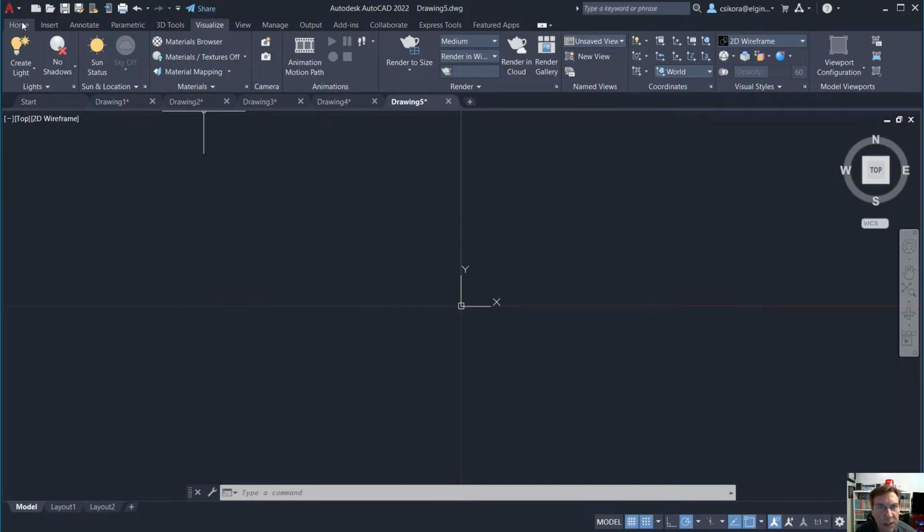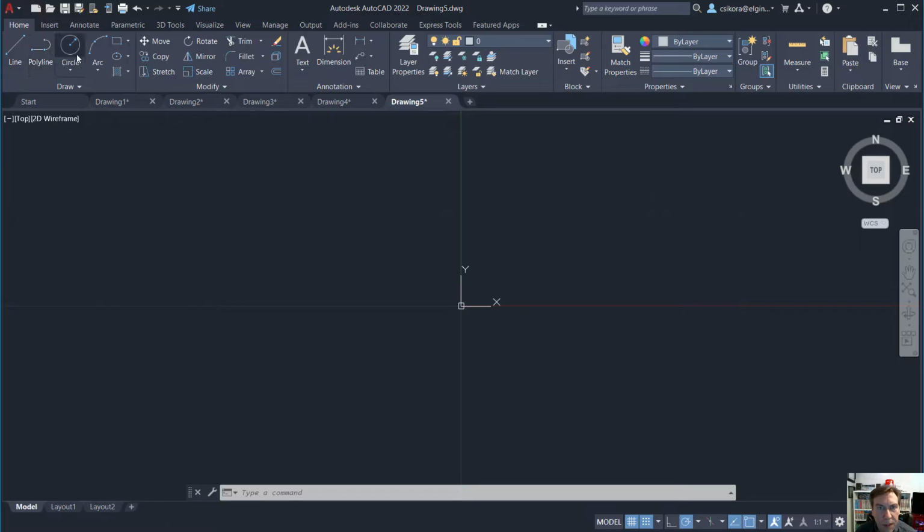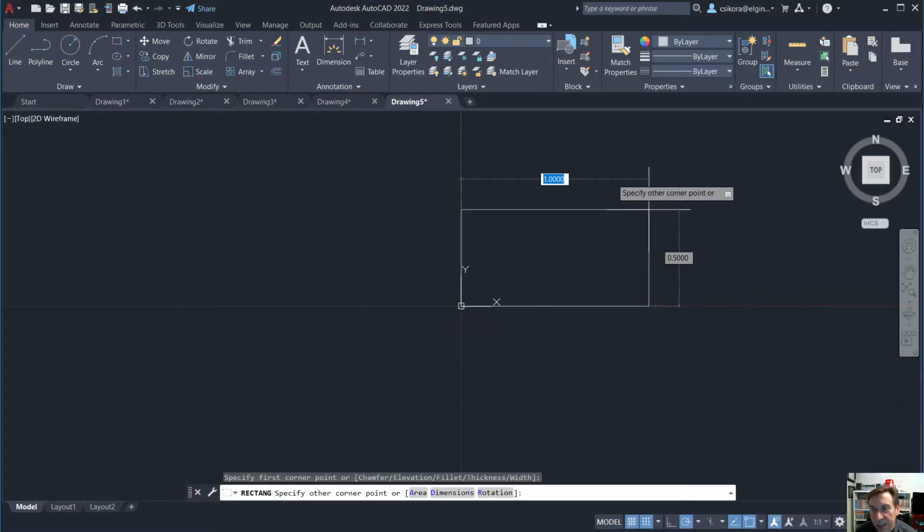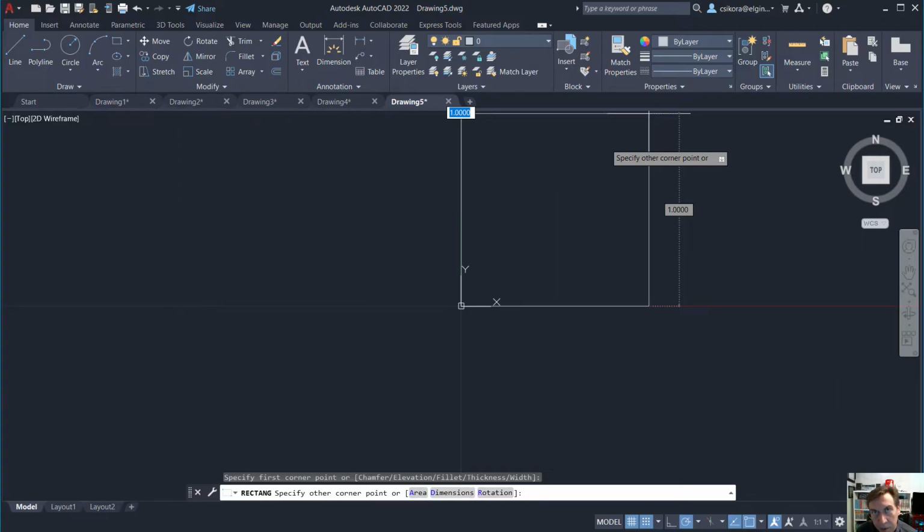So let's go to the Home tab, and then over here find the corner rectangle and hover over the origin. That's your zero marker in space, as you can see over to the lower right of your cursor. We're at 0, 0 because it's snapping to that, because we have our grid turned on. Let's click and drag to the upper right, and it's going to snap by half-inch increments. But what we can do here, you'll see there are little dimension areas in there that you can enter dimensions into right now. For example, it's the X dimension.